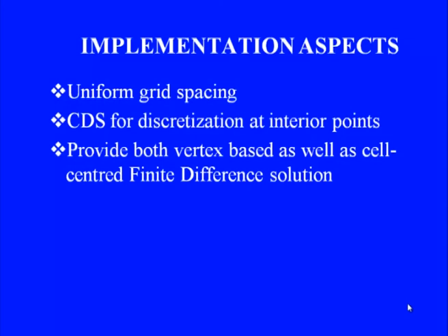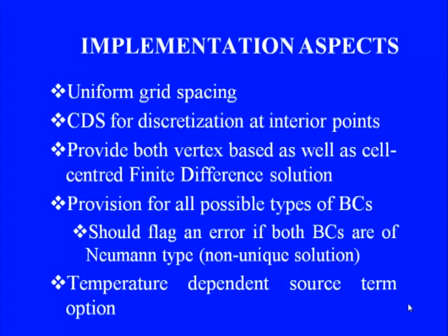Once again, our implementation would assume uniform grid spacing and CDS for discretization, and we should ideally provide for both vertex based as well as cell centered finite difference solution algorithms in our code, and provision for all types of boundary conditions. Our source term would be temperature dependent.